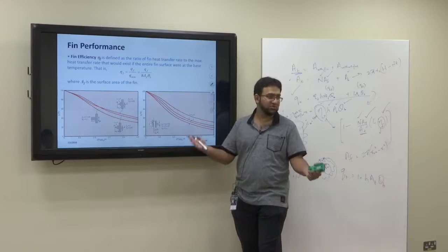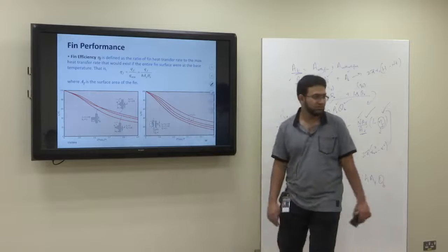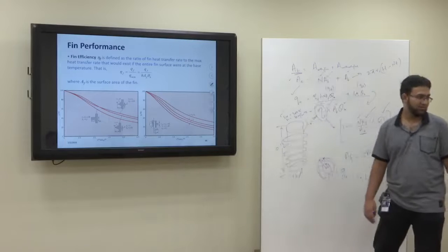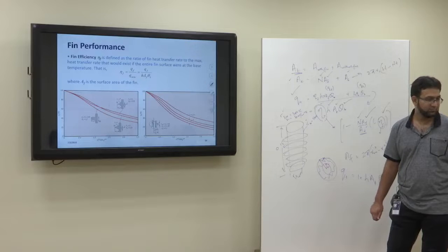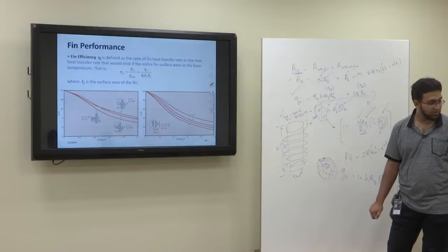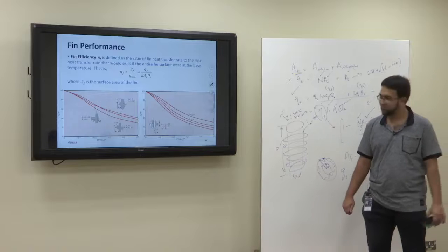R2 is known, T is known. So you get R2C. Is it clear? Yeah, so R2 is from the center of the cylinder to the tip of the fin. They added the length of the actual fin itself. Yeah, just the actual fin. Okay.